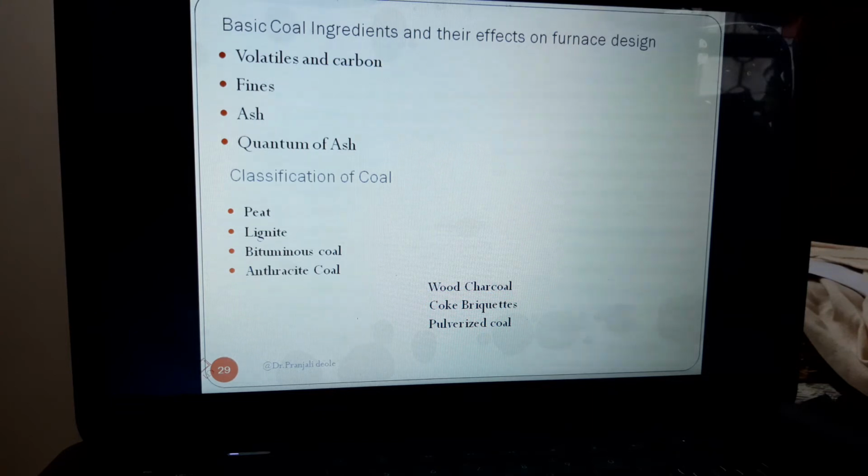Slow rate of burning tends to develop lower furnace temperature and induces a good amount of air through the coal bed without taking part in combustion. Therefore, slow rate of burning of high ash coal needs much larger excess air to be supplied, and thereby further reduces the furnace temperature.